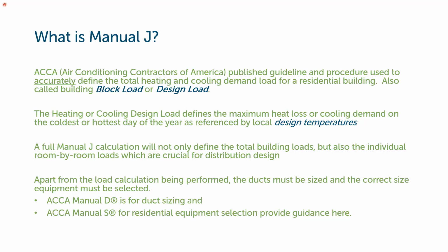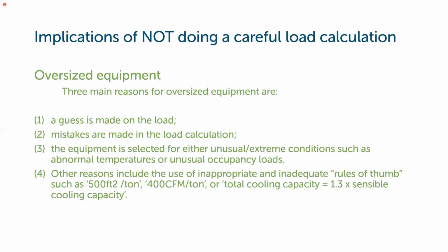So Manual J, accurate load calculations are crucial for any new building especially, and also should be getting done for any, like I said, system replacement. That's also a requirement called out under code. So that's been in the code for many, many years. And there's certainly implications for not paying attention to accurate load calculations, especially now as we are certainly seeing much lower design loads with buildings because of the requirements of code and just general industry adopted standards for construction at this point.